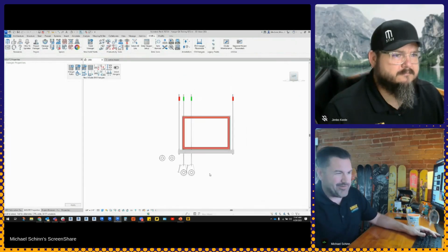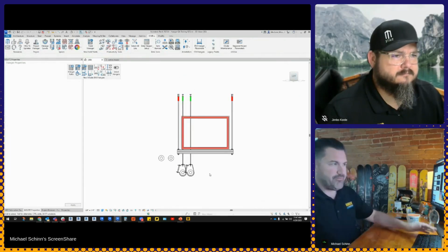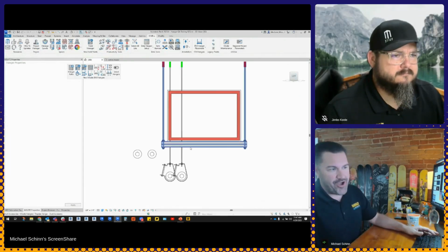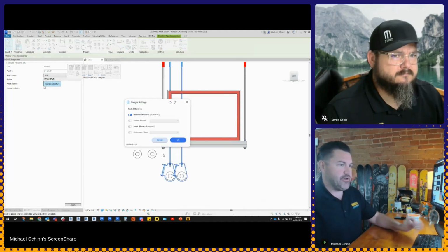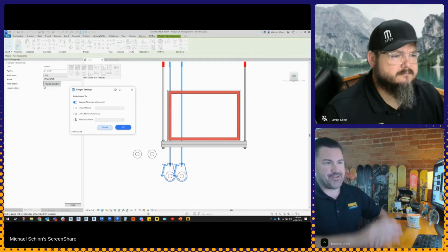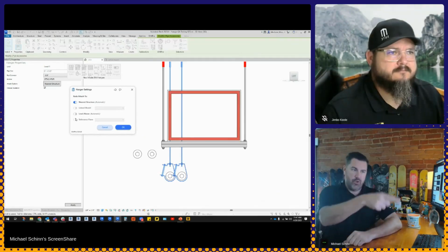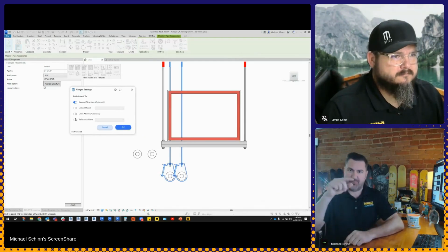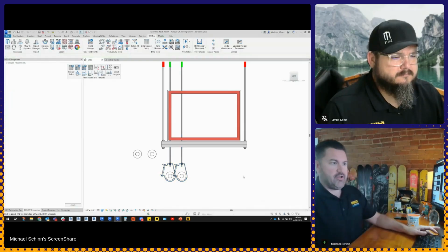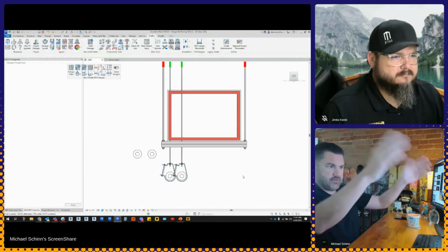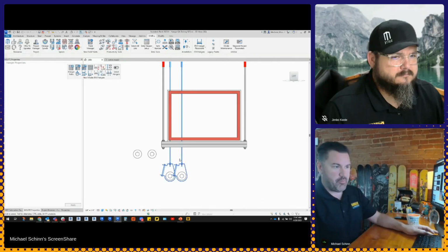I don't like workarounds, but the idea is you can draw a reference plane, tell these hangers to go to the nearest structure, and connect those to the reference plane. But we want to be able to actually say, like Triple H, I want to hang hangers from that hanger. So being able to quickly say, for that whole run and all those hangers above me, grab them all and say hang onto that. So features along those lines are what we're looking for.